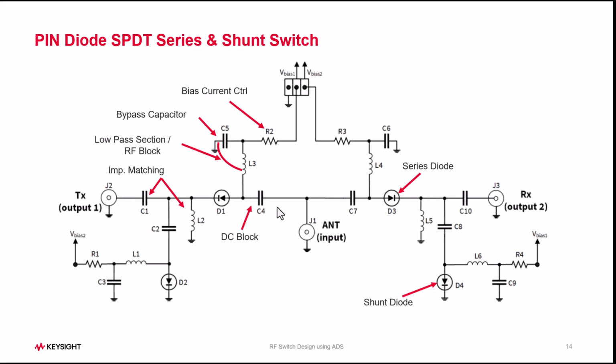Now in terms of the schematic configuration, here is a snapshot of the SPDT switch topology which we will implement. I have marked some important components in your switch design, which is here for you to see. One important thing, if you draw a vertical line around the antenna input, you can see this is almost a mirror image on left and right side. And when we are dealing with switch design, it is preferable to keep the values of these components symmetrical so that you can have similar performance in both paths of the switch.